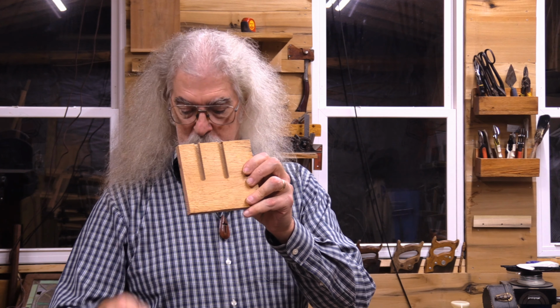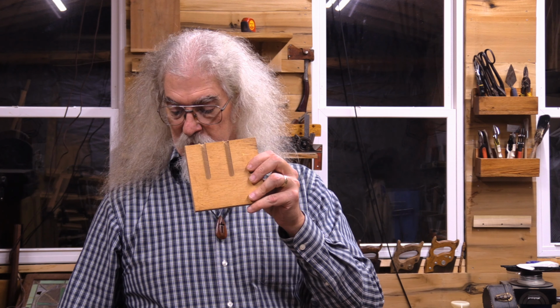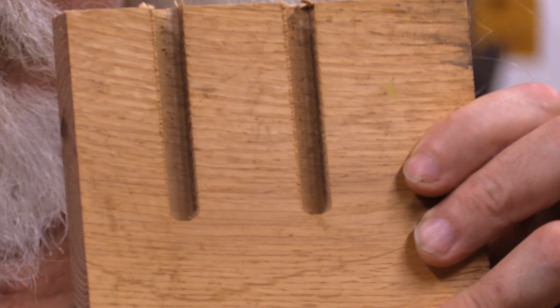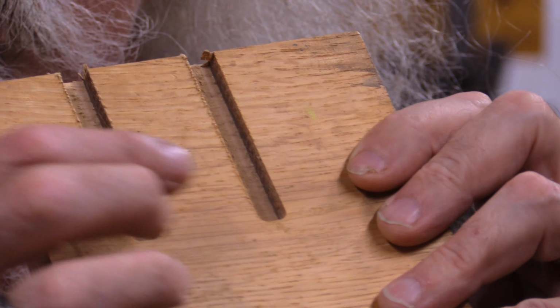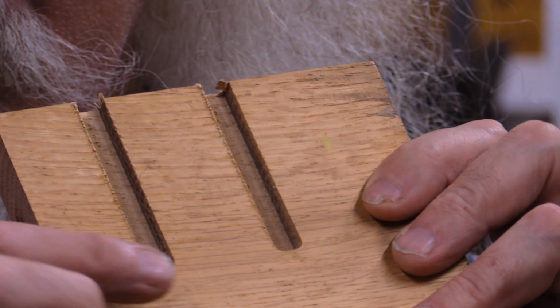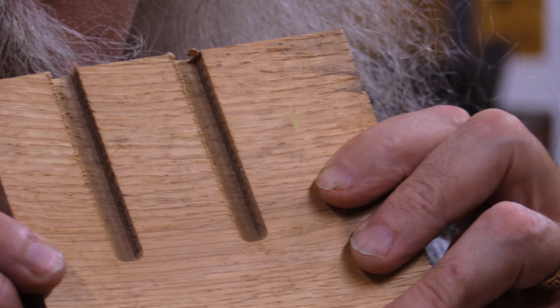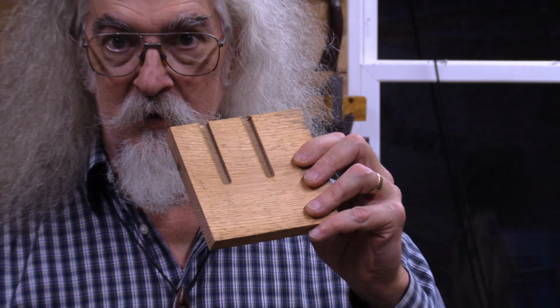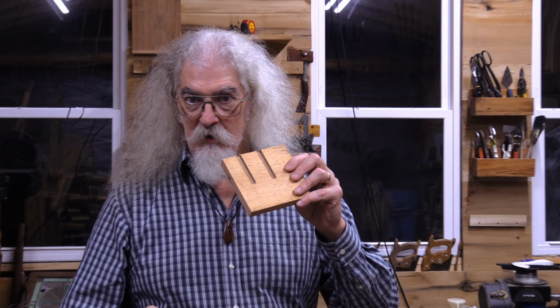This is the piece of wood here, right off of the CNC machine. See if I can keep that in focus. And you can see this came out really nice. Obviously you saw maybe a little bit of smoke if you were watching the CNC portion of that. And I'm using a 1/4 inch spiral downcut bit, and these edges are a little rough. So I think that bit needs to be sharpened. But in general, it came out really nice. And the actual ones, I just hit them on a big belt sander and cleaned it all up.